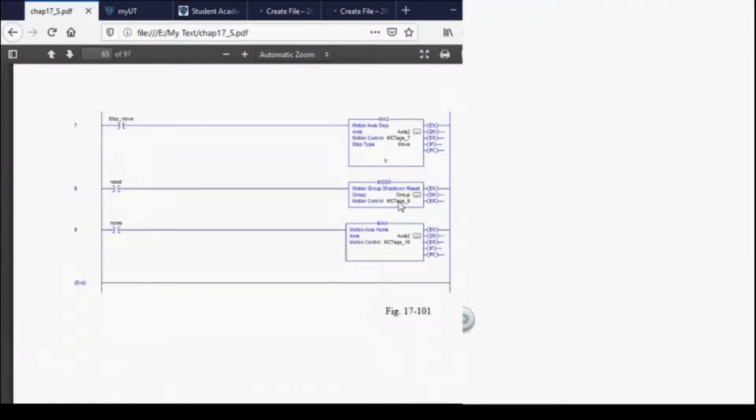This has feedback. Obviously, it's a servo, and it has feedback control, and you will hear it humming when it is in its working mode. Even though it may not be moving, it's motoring, even though it's at 0 speed, and you'll hear it hum. If you don't hear that hum, it's not going to take off and run for you. So that is the enable bit, and it is either enabled or it's not. And if it's not enabled, you do not hear the hum. If you do hear the hum, it is enabled and it's ready to go. So listen for that when you're doing the servo motor.